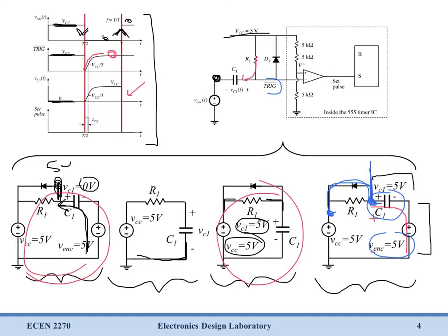Those are just when the circuit is sitting around, so we don't need to analyze them anymore. Our last state we see here, we know what happens. The node tries to transition too high, and our diode shorts the voltage out. But we don't really care about that because it's not setting any of our timing. So we can ignore this fourth equivalent circuit as well.